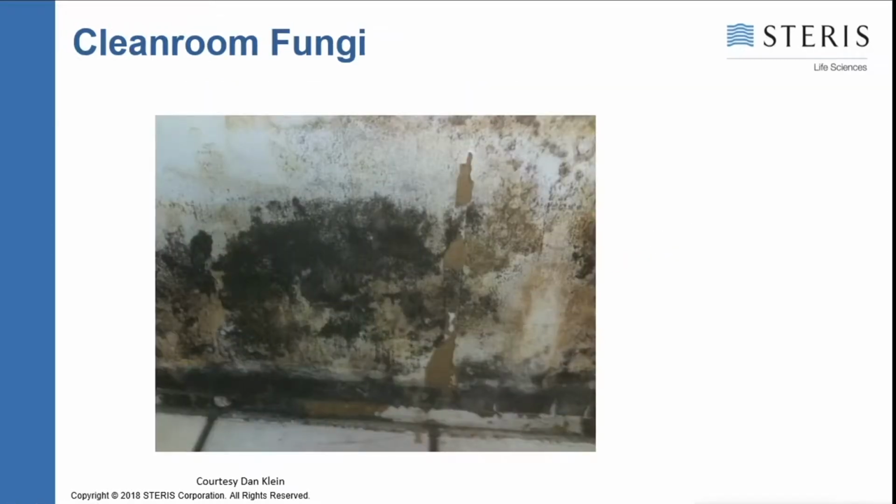And mold becomes a very big problem in the industry when it gets into clean rooms. This is an example where they were using a high impingement spraying device to spray the walls, and the spray velocity was way too high, so it punched out holes through the wall all the way to the sheetrock, and thus it became an endemic mold issue from Aspergillus and Stachybotrys, as you can see here. And that facility spent roughly $200 to $300 million to try to eradicate the mold contamination.